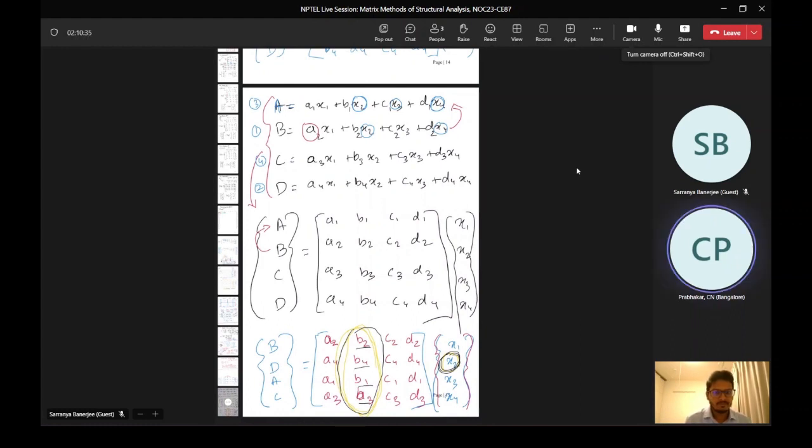You remember? Okay. The equations, whatever is on the right hand side, that also has to be changed, otherwise no. Just to make the difference in the load vector, we do the row operation, and to make the difference in the displacement vector, we do the column operation.